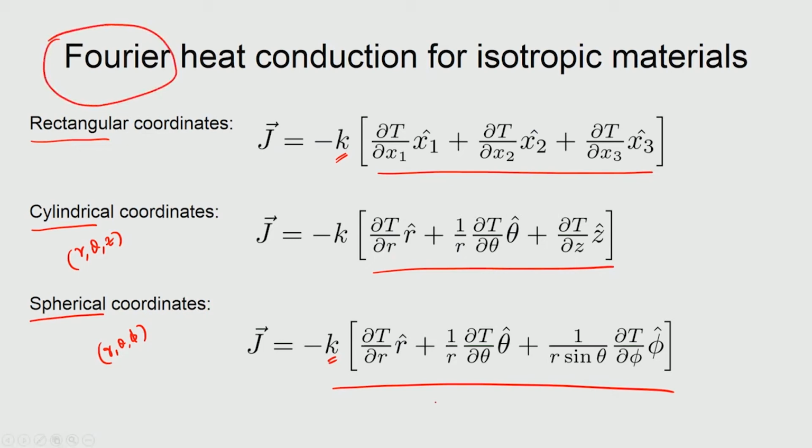Okay. So, in the realm of most of the engineering scenarios, we normally encounter only Fourier heat conduction, because non-Fourier heat conduction is out of the purview for our course. It normally happens when we have laser pulsing at time scales that are very small, like picosecond or so, but most of the engineering problems where the heating is done at the expected rates and pulsing is done in milliseconds or so, or even more, the Fourier conduction equation is valid, and that is what is written here.